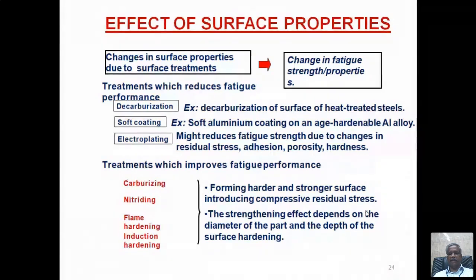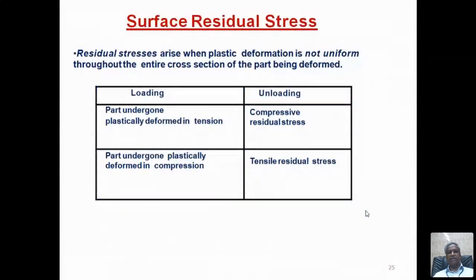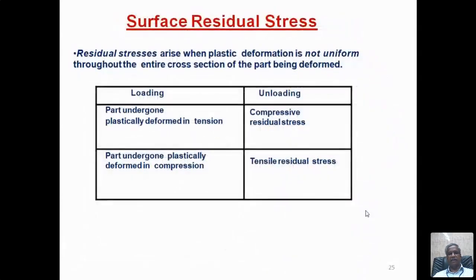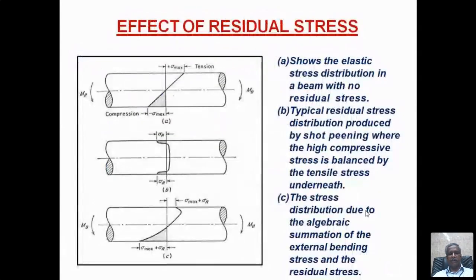If the compressive stresses are introduced, then the life will be more. Whatever post treatment you do, if it increases the compressive stress on the surface, then the fatigue life will be higher. So, surface residual stresses. I'll leave this and come back to it, because this diagram will explain it properly. Surface residual stress.